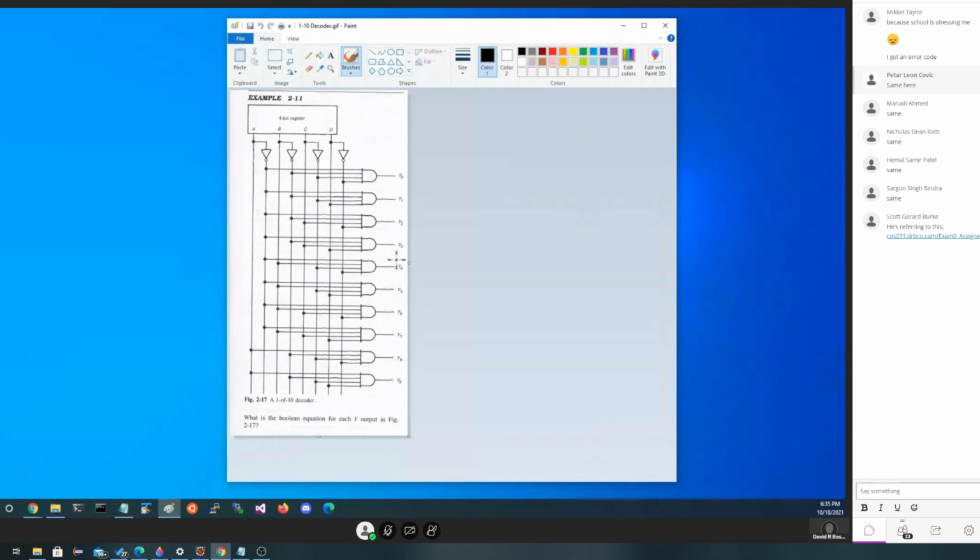Everybody remember that? Kind of give me a green thing. This was under digital components when we talked about this. This is sometimes called a decoder, a 1 of 10 decoder. Well, actually, that's on this sheet here, so that's what it's physically called in our world. If one of the numbers is picked that doesn't have an output, well, nothing turns on. All the outputs would be turned off.